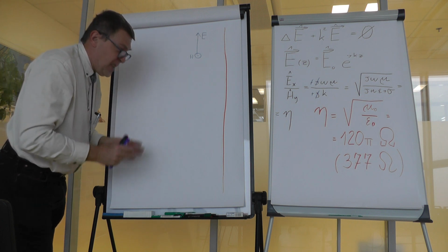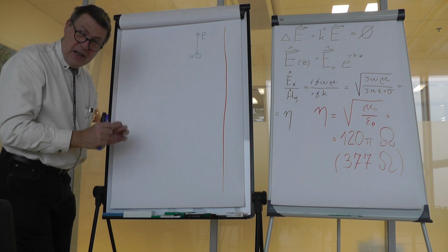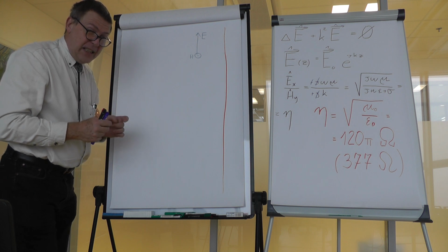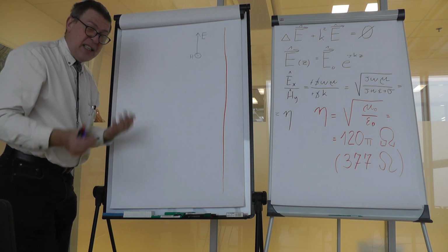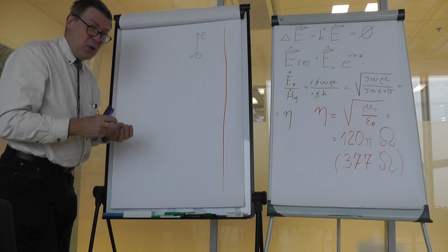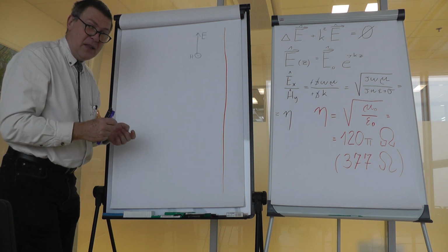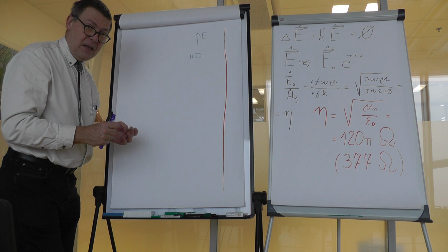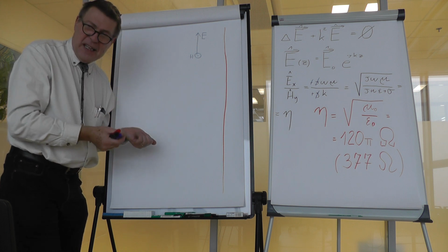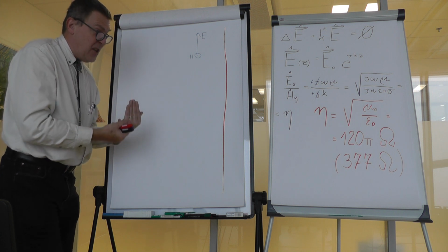And we have first stated that this is a perfect conductor, so that a perfect conductor is first defined by the fact that it has so many movable charges inside it that it is impossible to create a tangential electric field strength component within it. It's impossible to create any electric field component within it, but for us it's important that it also applies to the tangential field.